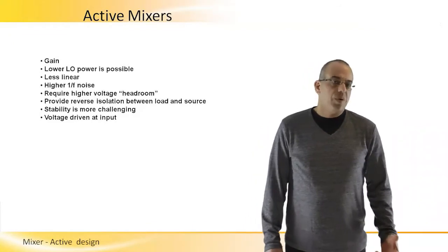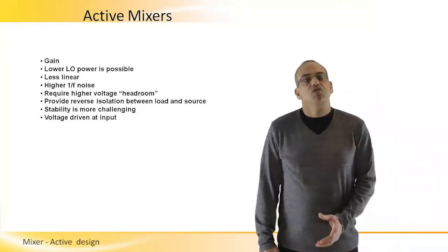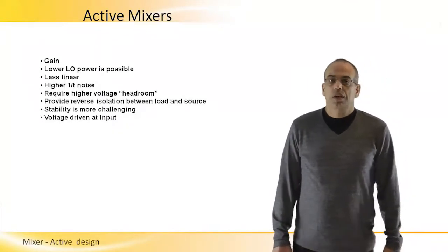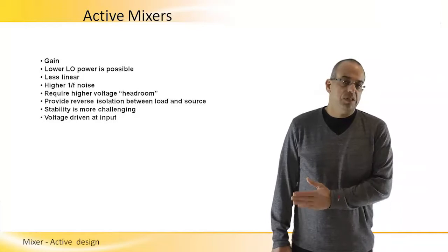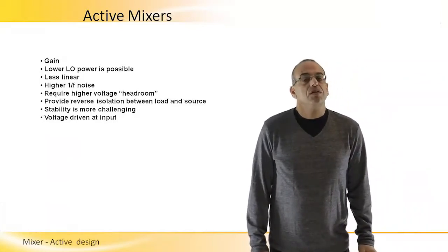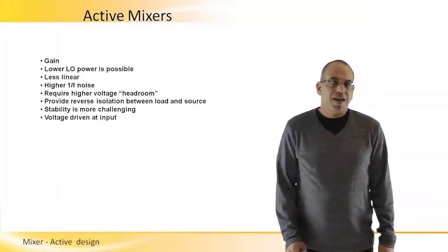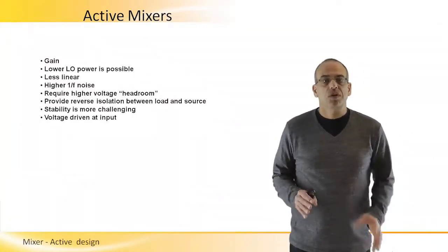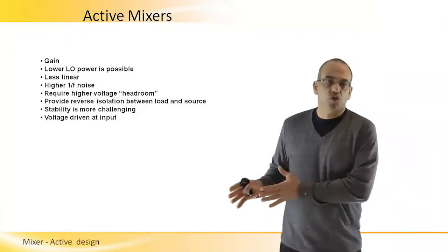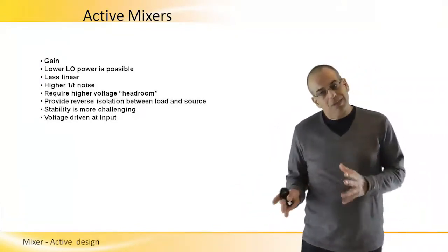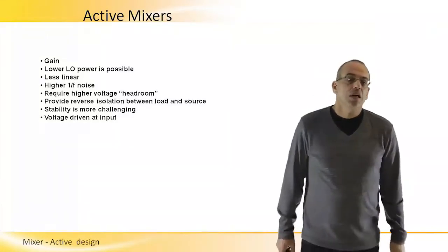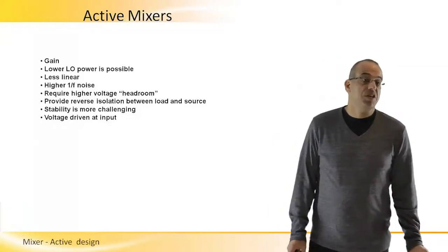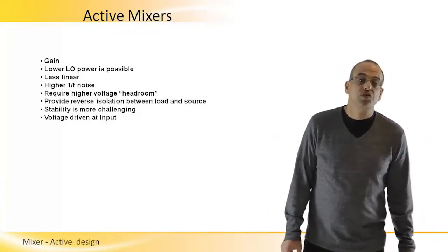It is very likely that in active mixer design we will need a lower LO power than we did when we designed passive mixers, because with passive mixers we were really looking at this as close as possible to ideal switch performance, which here is less critical. On the negative side, active mixers will usually be less linear than passive designs.